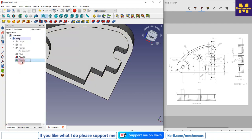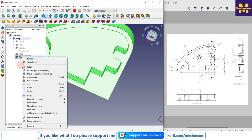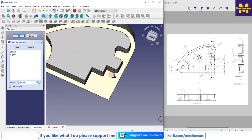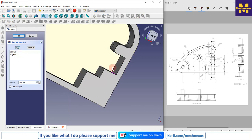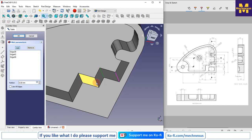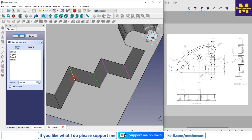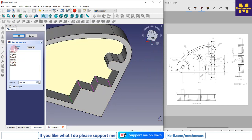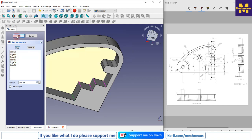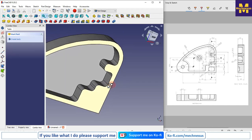So I will delete the second one, and I will add the edges in my first one. So while you are selecting the edge from the fillet parameter, you do not need to press the control key. So now it has been adapted.